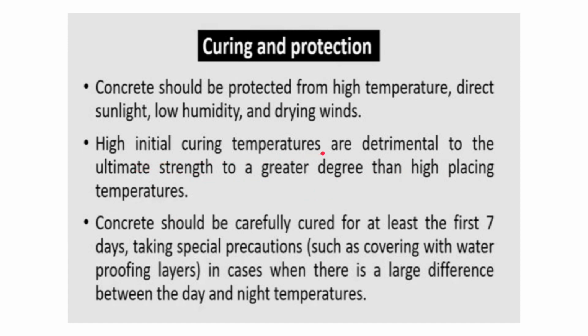So this initial curing temperature should be as low as possible, and that can be done by lowering the rate of hydration. Concrete should be carefully cured for at least the first 7 days, taking special precautions such as covering with waterproofing layers, in cases when there is a large difference between the day and night temperatures.